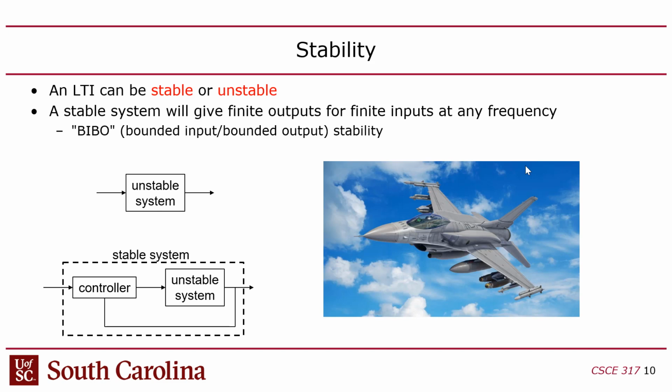So you've got an input. The terminology is a little weird because the system has an input. So the controller generates an input to the system. The controller has an input as well, but that's not the same type of input. This is a set point, and this is a manipulated variable. And then you have this signal coming back from the system back in the controller, and that's the process variable.